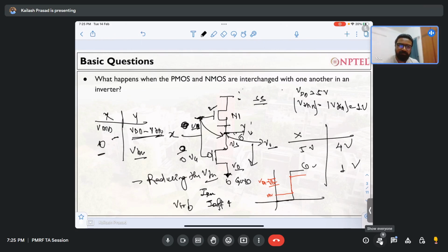Suppose you have a mobile which is working very fast, but as soon as you remove the charger, the battery goes down in one hour. Do you want that kind of mobile? The answer is no. Your battery should last. The static power, the leakage of whatever circuit you are designing, should be as low as possible. If you just keep the mobile like that, ideally the battery should not degrade, but we still have some leakage. That's the reason it degrades over time.